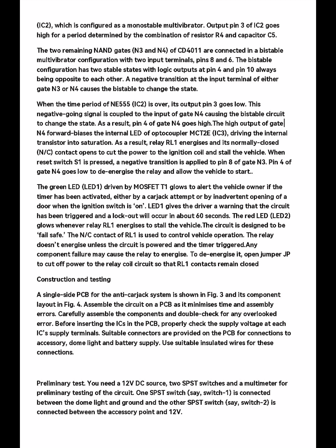The high output of gate N4 forward biases the internal LED of optocoupler MCT2E IC3, driving the internal transistor into saturation. As a result, relay RL1 energizes and its normally closed (NC) contact opens to cut the power to the ignition coil and stall the vehicle. When reset switch S1 is pressed, a negative transition is applied to pin 8 of gate N3. Pin 4 of gate N4 goes low to de-energize the relay and allow the vehicle to start.